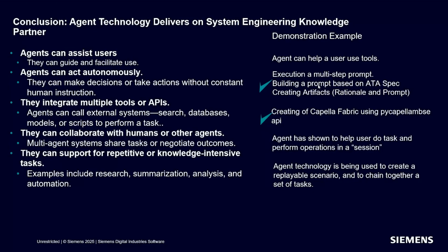As you notice, the actual image of the diagram doesn't become that important for the Capella model because it's actually working on the model representation. The diagram is just used as a collection that I can feed the large language model. The fabric: I'm using Pi Capella MBSE APIs to create the fabric, and basically just pulling it in. Creating the fabric is essentially a YAML representation, which is very easy to read. Other representations, such as JSON, could be used instead. And in the case of SysML v2, the textual syntax works pretty well as the fabric.